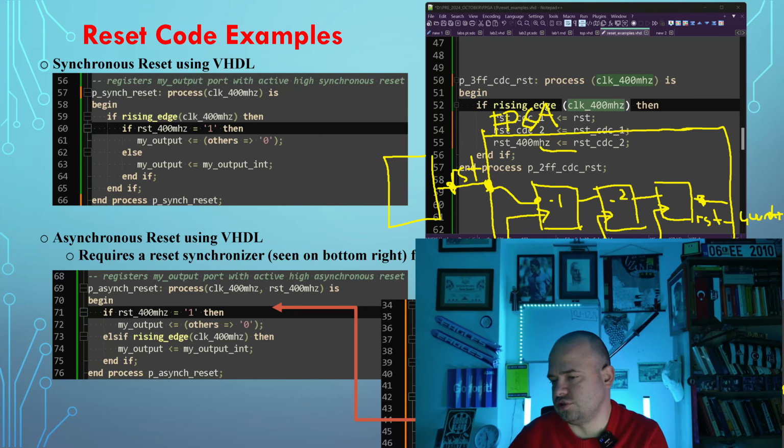But there are some cases where the FPGA is capable of providing positive slacks for, let's say, 400 MHz, but still the MTBF using 2 flip-flops is not that good. It is like 1, 2 years, 3 years.